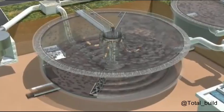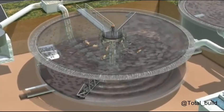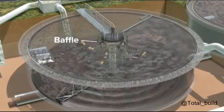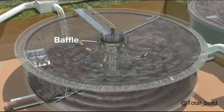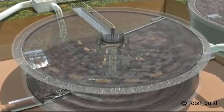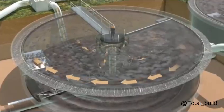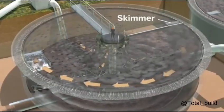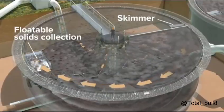Water flows in at the center of large circular basins called sedimentation tanks. A baffle slows down the flow rate to aid the settling process. Floatable solids, like grease and oil, drift to the top of the tank. A rotating skimmer continually pushes this material into a collection trough.